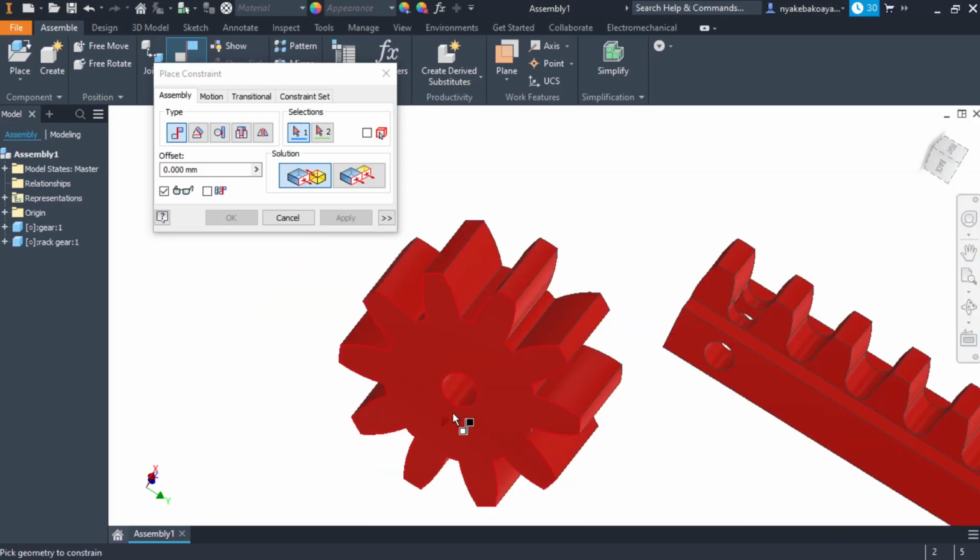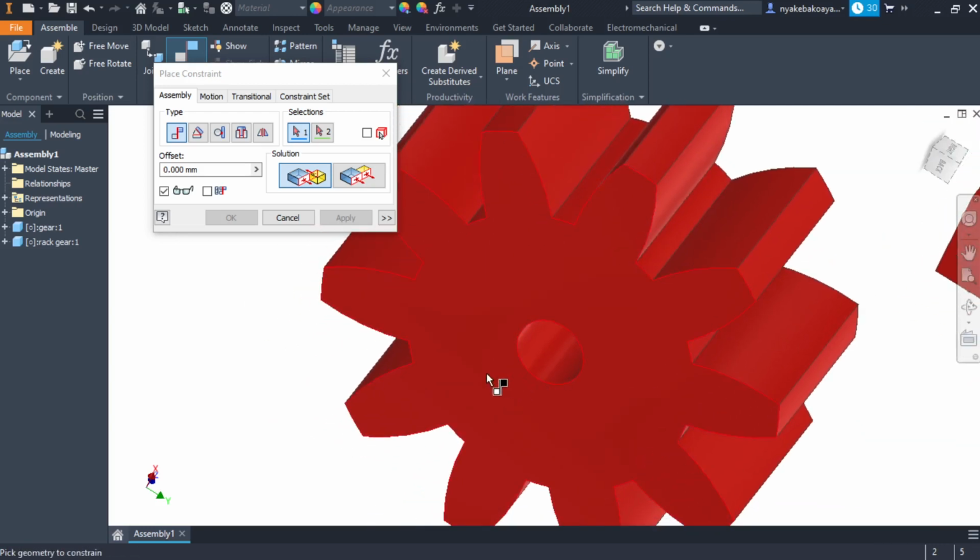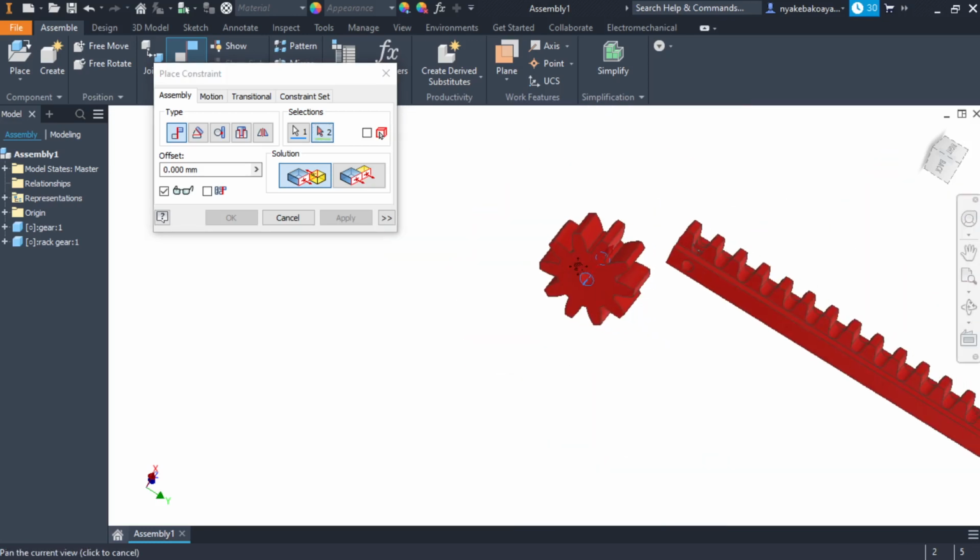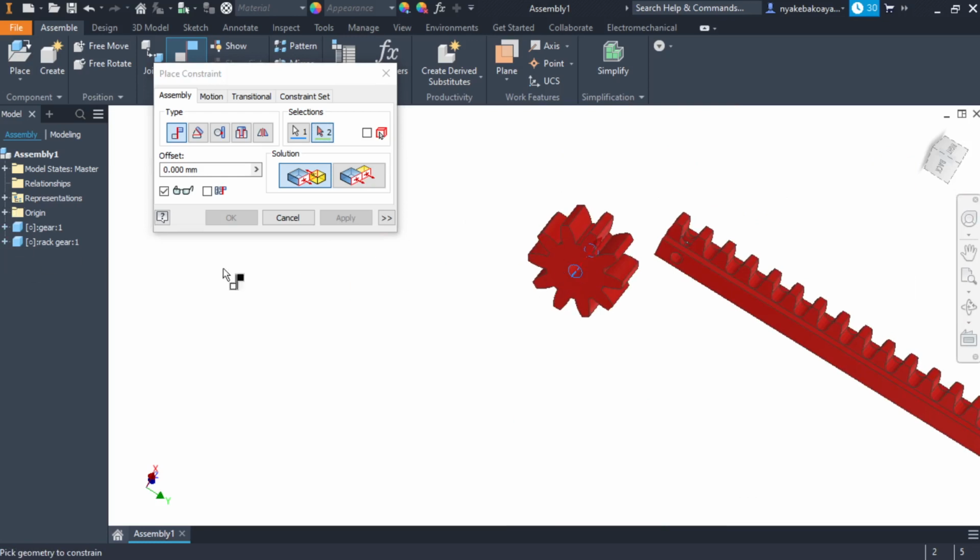One thing I always like to do here, or for anything that you could be doing, is that once you start hovering the cursor, you start seeing a set of points, those dots, and then that central axis line. So click that, because anywhere you hover, as long as the geometry of your model is circular, that one is going to pop up. All right, click on that circular face inside.